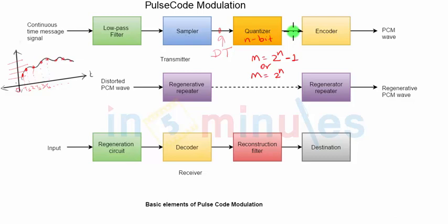When we talk about the digital signal, we want the output of the encoder to be represented in the form of ones and zeros. Now there could be various ways in which this can be done. For example, logic 1 can be represented using plus 5 volts and logic 0 can be represented using 0 volts. This could be one way in which you can represent your signal. This is called unipolar representation of the digital signal.